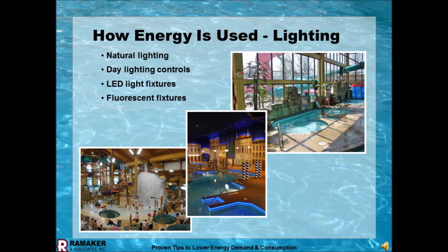After about 2 years of collection, you're going to start to understand your trend, and you can look at it and say, room occupancy is going to be down for the next 3 days. Let's back the recirc rates down on these pools back to what the code is, as opposed to having the higher turnover rate that we need for when we're full on the weekend. It's again getting to know your systems.